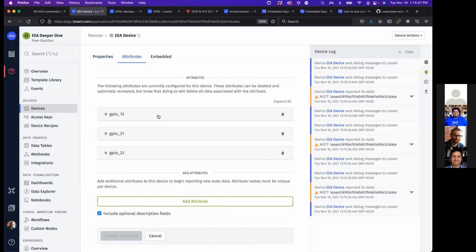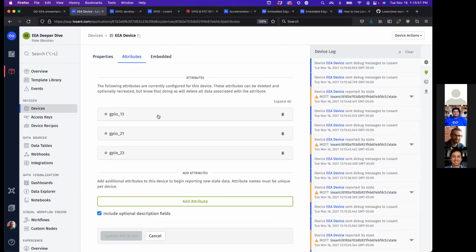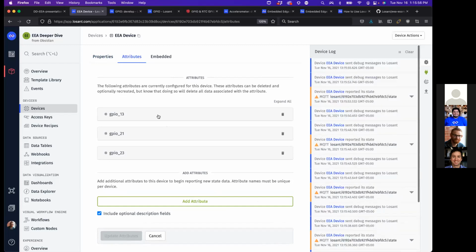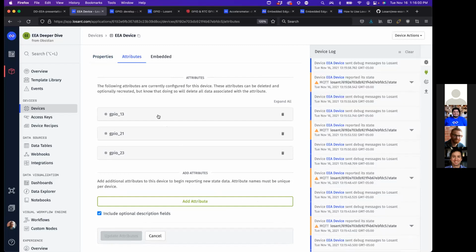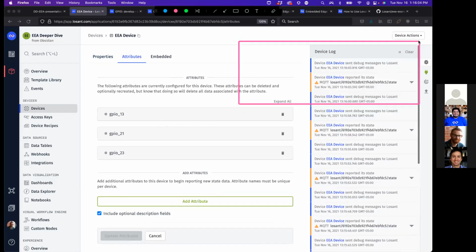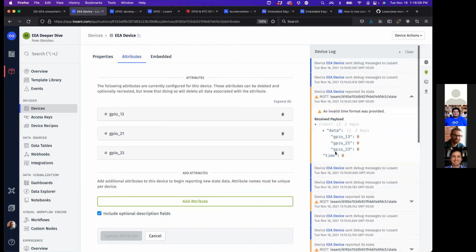I'll show the workflow in a minute, but what this workflow is doing is controlling and then reporting some GPIO. So showing how an embedded workflow works with those really low level peripherals, in this case, general purpose input output, that's available on these modules. And then in the debug panel over here, you'll see some data coming in. We pause that, and you see it's reporting some state in the value of these GPIO inputs and outputs.